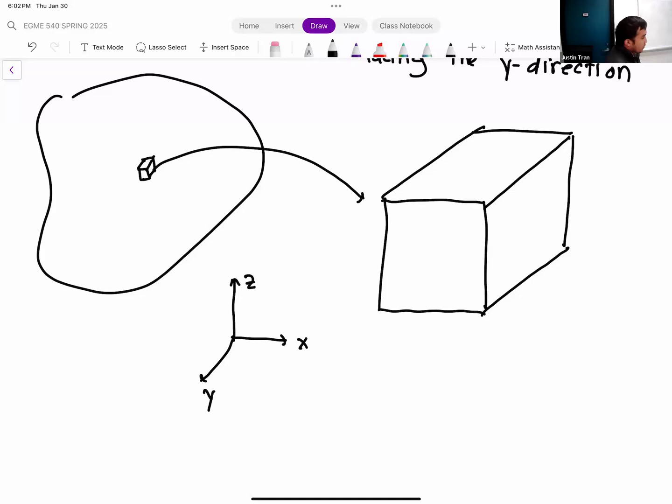Okay. So let's start with the normal stresses, because those are easiest to visualize. Let me use purple for the normal stresses. Remember, normal stresses act perpendicular to the face, and they act to either pull this apart or compress it together. So we have three components, and I'm going to draw them on the three sides of the cube that we can see.